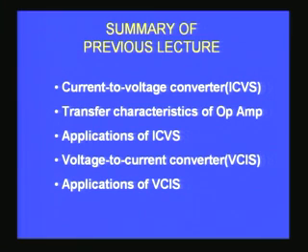of the virtual earth. You might recall that the input voltages between the 2 input terminals of an operational amplifier cannot be larger than plus or minus about 200 microvolt in a typical case. We also saw applications of the current voltage converter.